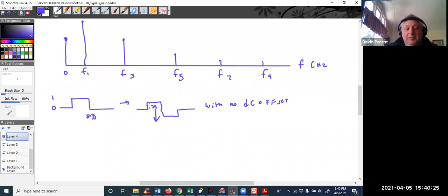Don't worry about the amplitude. You just want a square wave, because if it's too small, you're going to use an op-amp circuit to amplify it. If it's too big, you're going to use an op-amp circuit to make it smaller. So really, all we want is some kind of filter, right?